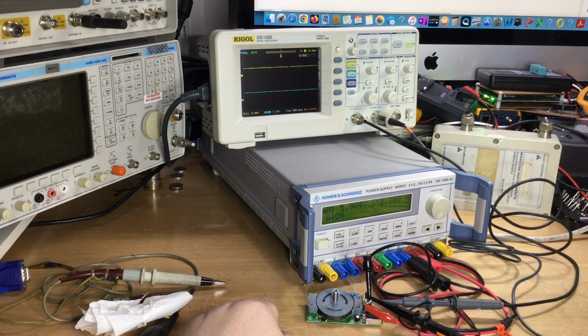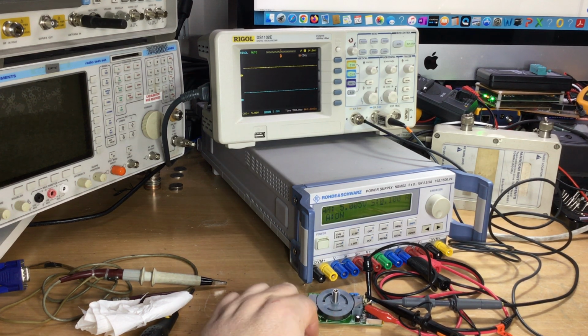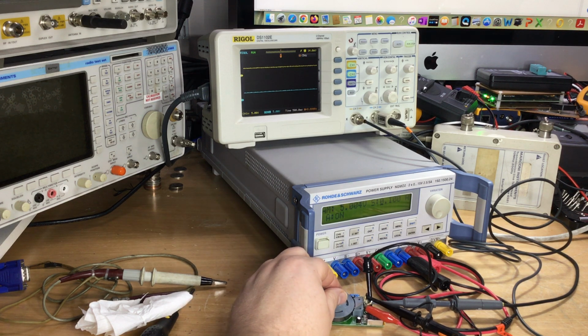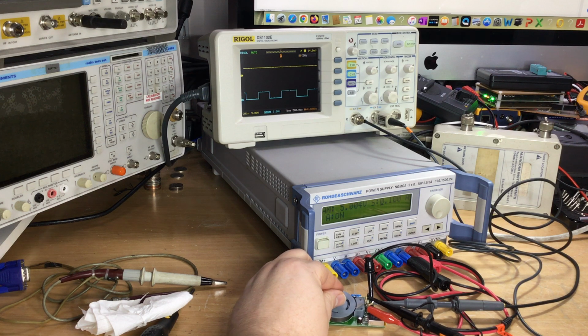Okay, put it all back together, but it's still the same. So what I've done, I've bent one of the Hall effect sensors away from the wheel, which is this one here, just to isolate which one it is out of the two. So when I turn the wheel on this, because we're still looking at both channels, you can clearly see in a moment the bottom trace is more or less uniform, so that's good. But the top trace isn't measuring anything at the moment, because obviously the Hall effect sensor has been pulled away from the magnet.